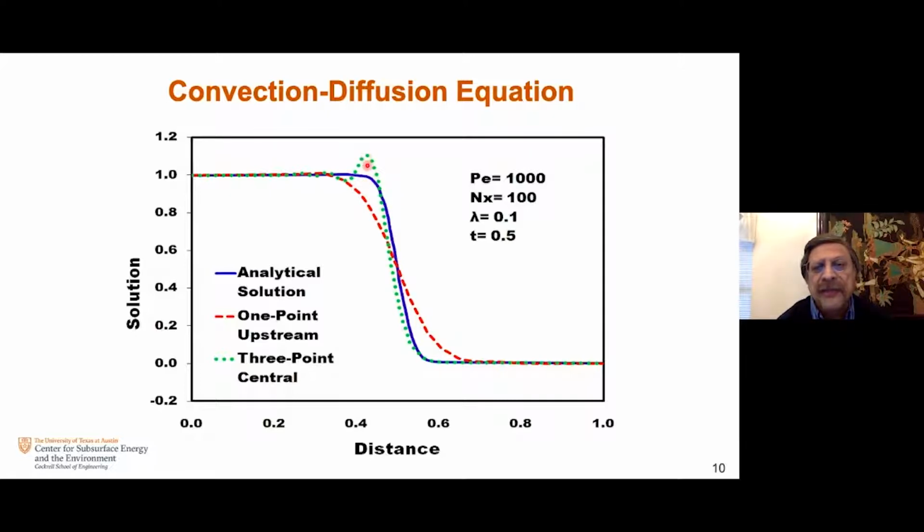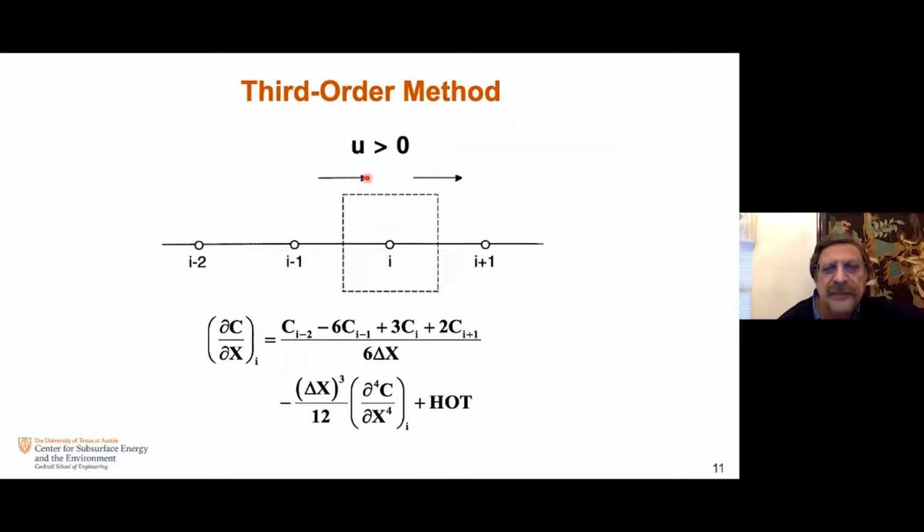However, the error in this one is not necessarily any smaller or larger than the backward difference upwinding, but the upwind looks good because it doesn't deviate in oscillatory results, and we feel it's better, but both of them do have large errors. Now, if you refine the grid, eventually the upwind scheme is going to go very close to the exact solution, but the central differencing continues to have some very small oscillations.